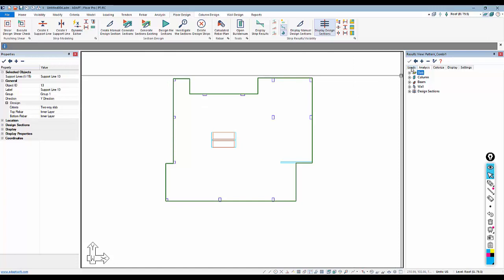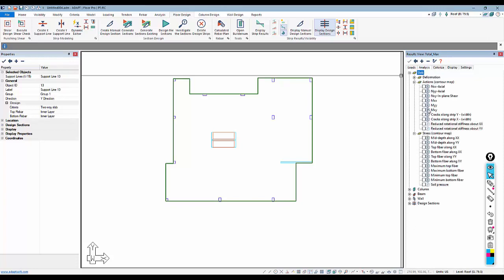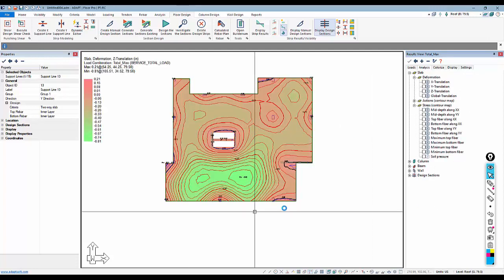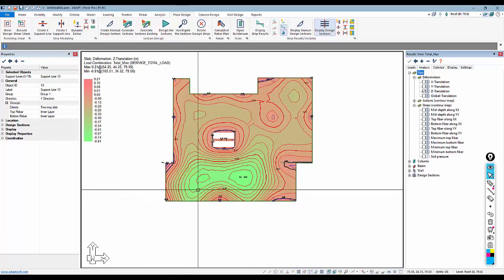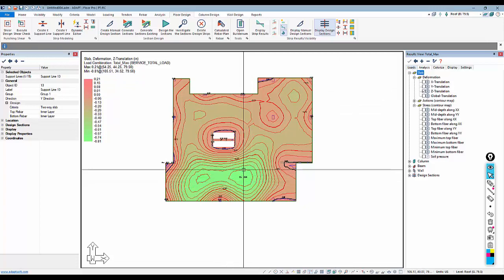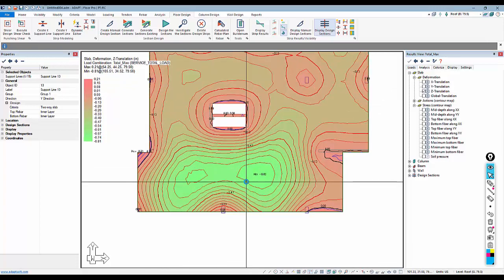If we go, for example, to the skip max and min, let's go ahead and collapse that. I'll collapse this also. We're going to go to the service combination here. We have this one called total max, and if we go ahead and produce the deflection result for total max, this just indicates an envelope of all patterns based on that maximum value, maximum meaning maximum vertical deflection downward.